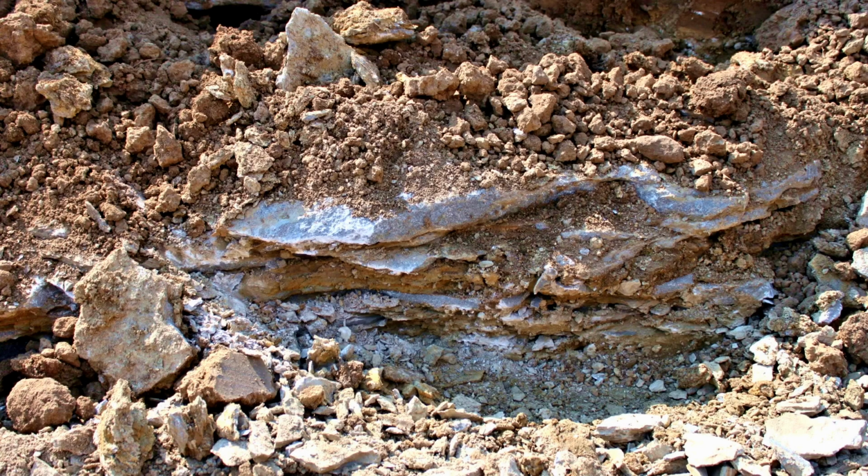It is very difficult, if not impossible, to build a groundwater dam where limestone bedrock is found in the bottom of the test hole. See these layers of limestone that we've cut through using the bucket on the excavator? These layers are permeable. They're not a good foundation for a groundwater dam. Another sign that one should not build a groundwater dam at this location is that we don't see any water pooling on the top of that limestone. This shows that surface water is soaking into the ground and under the limestone layer.